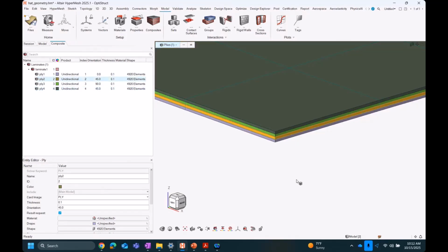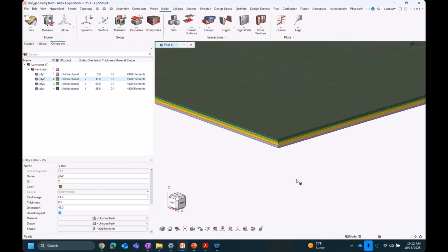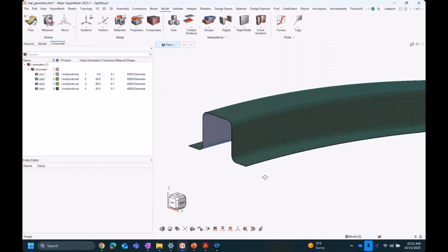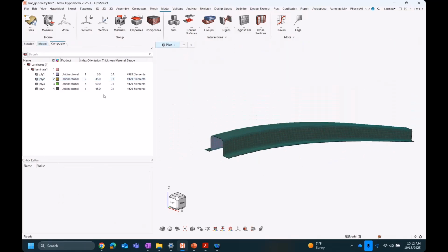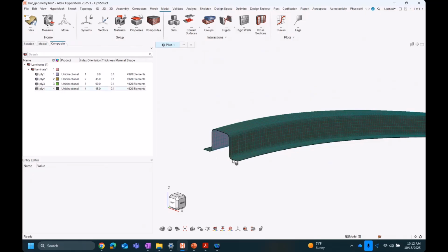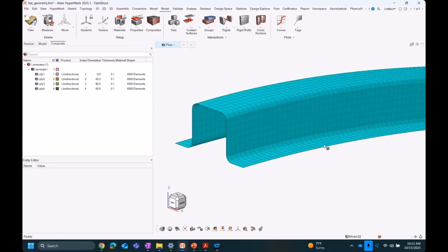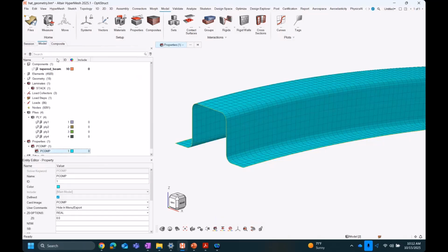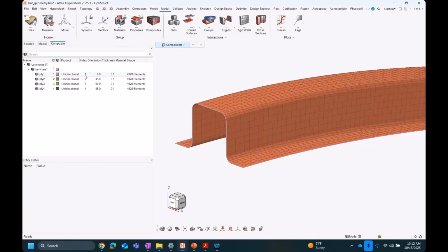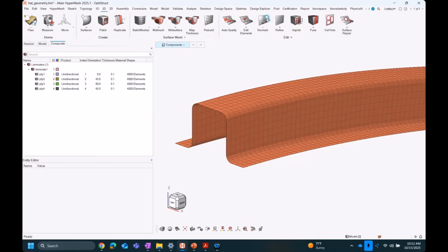So again, this is what we think is one of the big benefits of the ply-based modeling approach. Okay, and so of course there's some other things you've got to check with defining your composite model. One of them being the element normals. I mentioned I did a zero offset for the p-comp. So again, that's going to stack the plies starting from index 1, 2, 3, 4, etc. in the element normal direction. So we can check that if we go to D and review orientation.